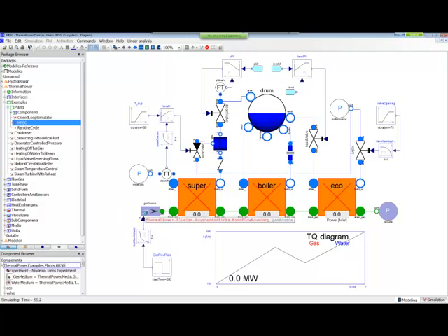And then you want to use the energy in that gas flow. So you feed it through three different heat exchangers, and the heat here generates enough heat to vaporize some water, so it becomes steam. And after it goes here, you can, for example, connect it to a steam turbine and generate some power.